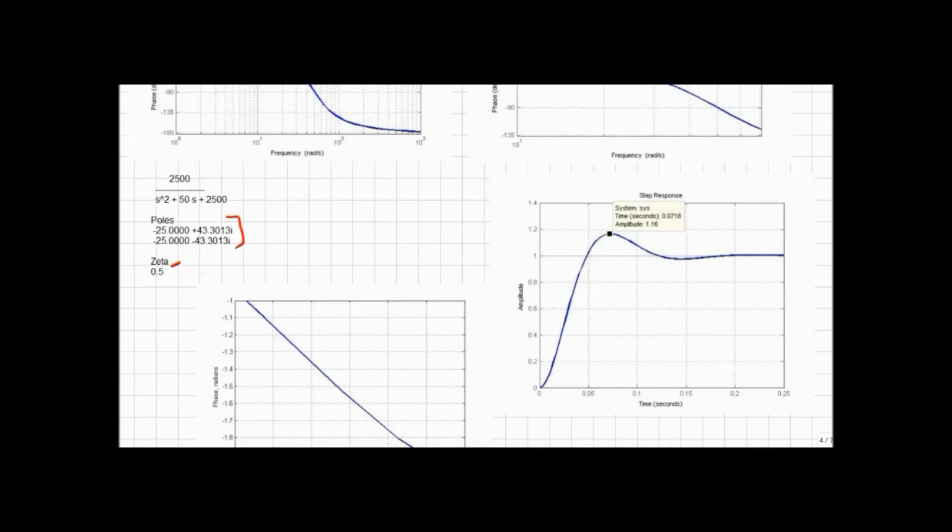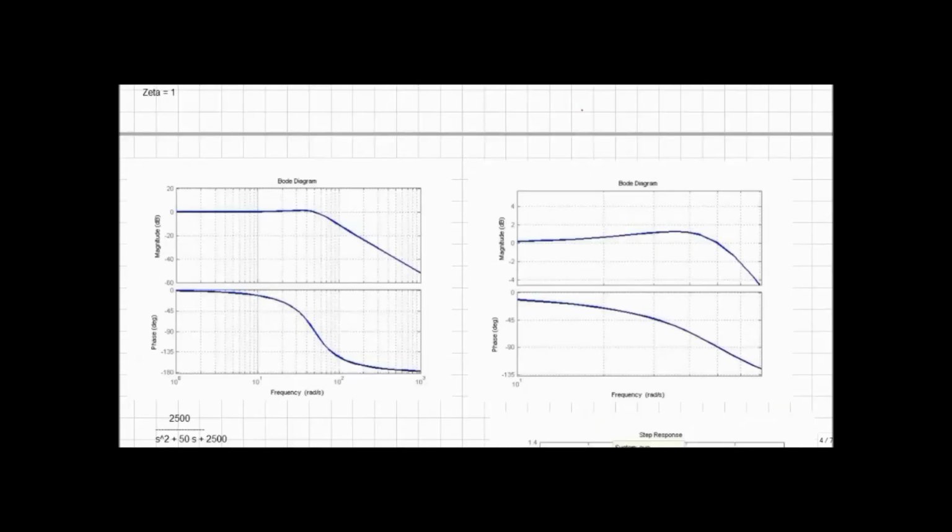I can't use the log decrement or anything like that because there just isn't oscillation. But we can go back and look at our Bode plot, and I get a little bit of a peak there. It's not much. I've blown it up over here on the right, so you can see the peak, but even that isn't a lot to work with.